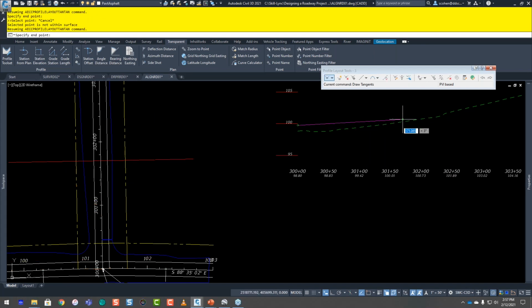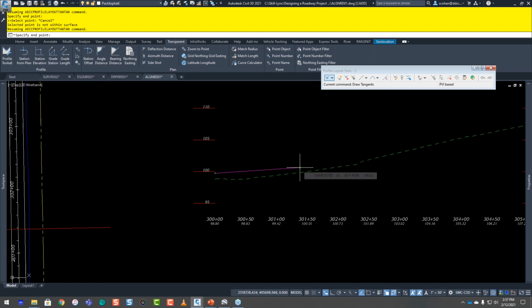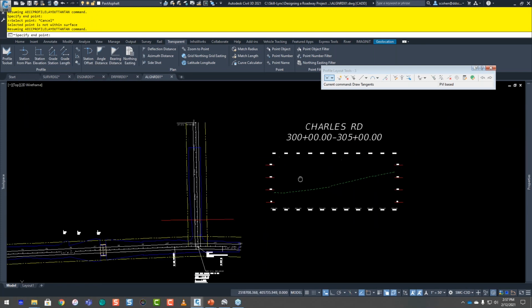once. That gets me out of the, oh, now it's working in this one. You got me. For some reason, it was working in that profile view. So now you can see it working. Well, now I want to do a profile grade length. I'm going to go down 2% for 12 feet, which is the width of my road, right?